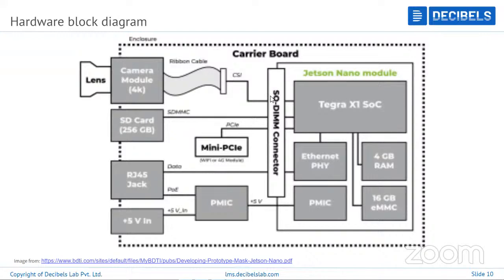Okay, any operational performance difference? Yeah, there is a lot of difference. If you see with respect to USB and CSI, these are two different interfaces, and based on these there are different communication protocols. Basically, if you have a USB port and you use a CSI port, CSI stands for camera serial interface. USB uses a serial bus. Compared to USB, CSI is much faster in terms of data transfer.